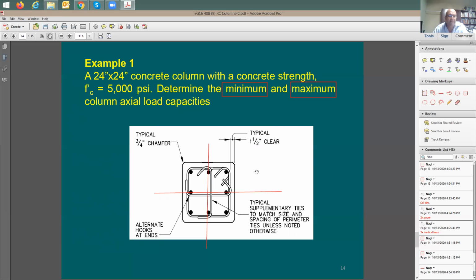Is 18 okay? No. I want to say no. It would be kind of overkill on this. No, you cannot put 18 rebars. How would you put them? Because the problem is you need to have symmetry, which means the amount of rebars that you put in each quarter here needs to be the same.